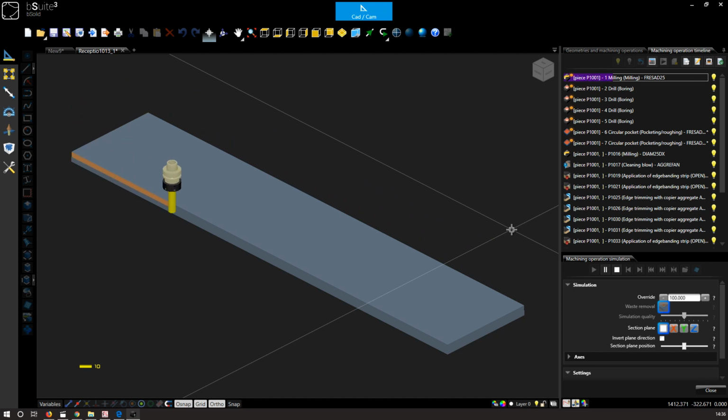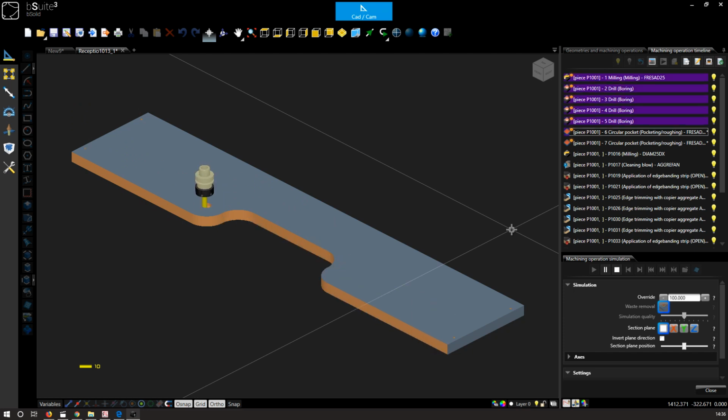This is a little quicker now. I've not moved the speed down so much. And there's our second formatting pass. Put a little less stress on the cutter. Okay, and we have some drills, and then we have our pocketing. So again, we have rules that will determine how many steps the pocket needs to be completed in, and the speed, direction, lead in, lead out, all configured directly from imos, so that all of these settings are done automatically, and the programs can just be run within the B Suite software.